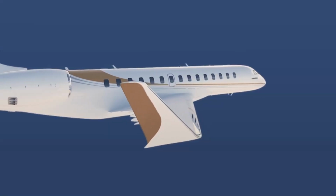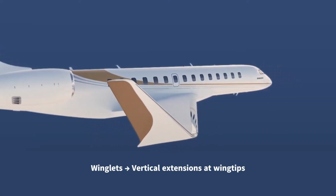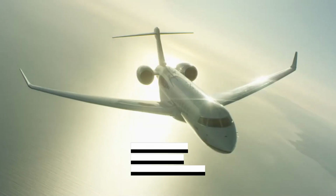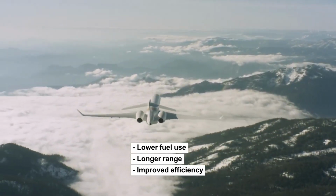One of the most recognizable additions to modern aircraft wings is the winglet. These are small, near-vertical extensions at the tips of the wings. Their main purpose is to reduce aerodynamic drag caused by wingtip vortices, the swirling air patterns that form as the airplane moves through the sky. By weakening these vortices, winglets cut down on induced drag, which in turn improves the aircraft's overall efficiency. The result is lower fuel consumption, extended range, and in many cases, smoother handling during flight.